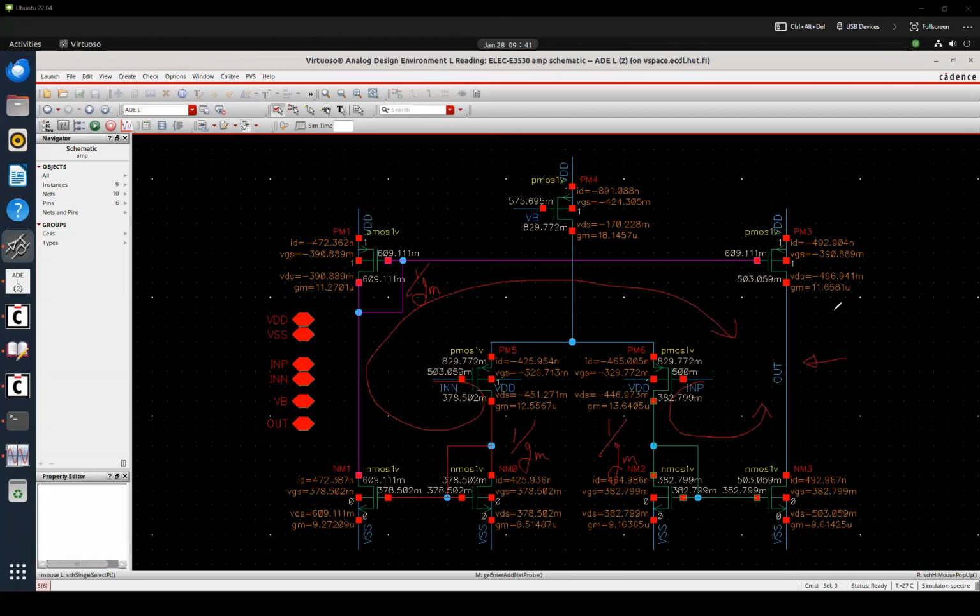Yes, correct. So RO1 parallel RO2, or we can also describe GDS1 parallel GDS2. This is a parallel resistance. Anyway, if you remember, GM RO is much larger than 1 in classical amplifier design. Then RO is much larger than 1 over GM.